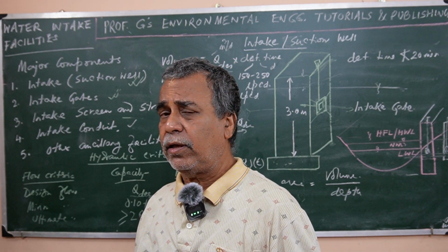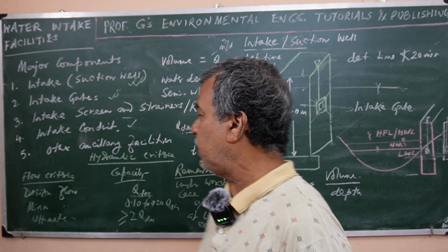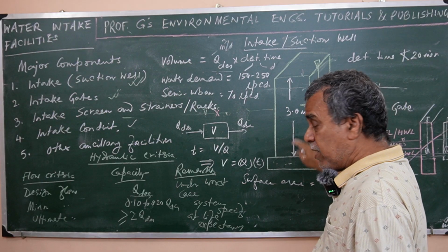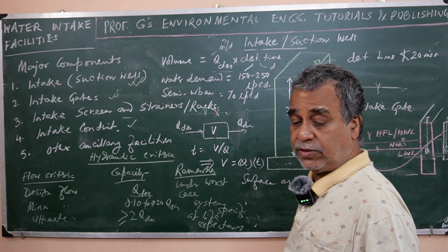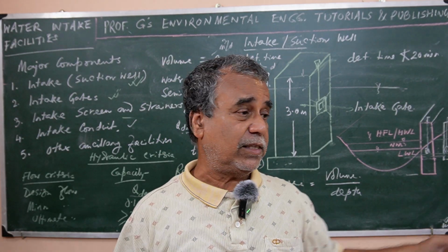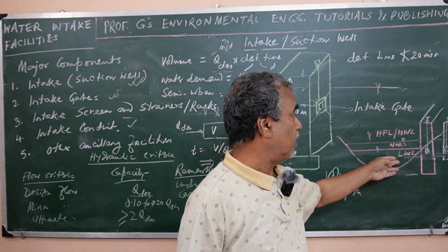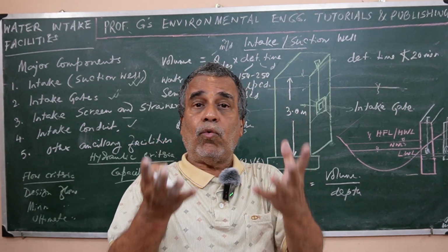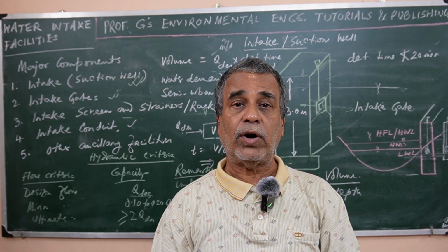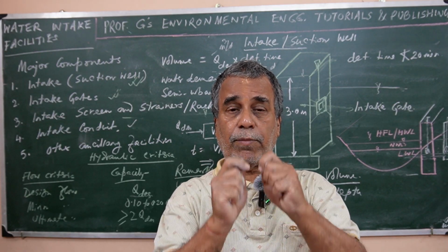Another thing to be mentioned here is that the weight of the entire structure must be considered while checking the structural stability of the intake well, because as it is on the river bank, there would be heavy water uplift pressure working on it from the bottom.